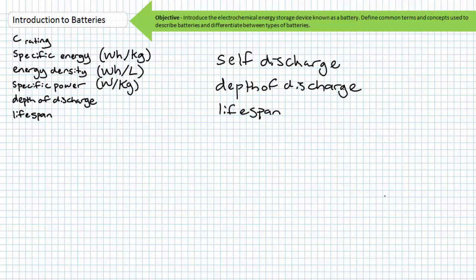It is for this reason that the charging and protection circuitry associated with lithium polymer cells needs to be reliable enough to prevent this occurrence from happening, and special handling precautions must be taken to prevent physical damage to the battery. A lead-acid battery, in contrast, is relatively more tolerant of overcharging. Notice I said relatively more tolerant. An excessively overcharged lead-acid battery can still be damaged due to swelling or loss of electrolyte, however, it isn't normally known to burst into uncontrollable flames.